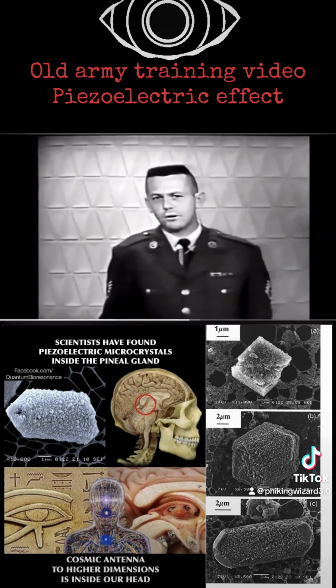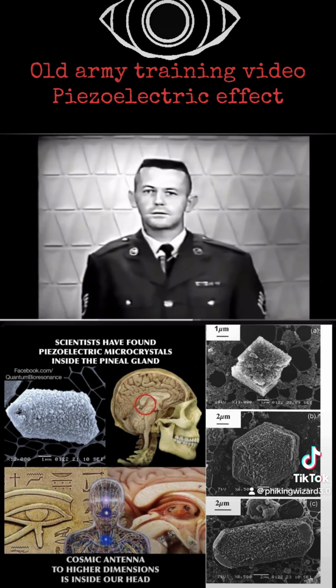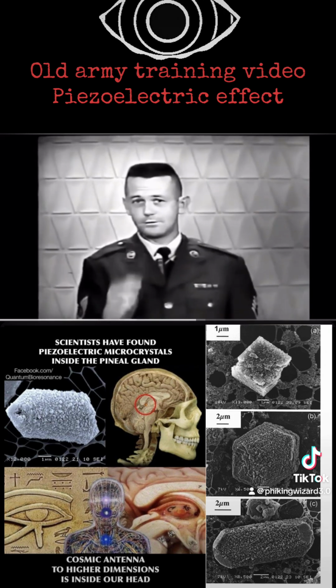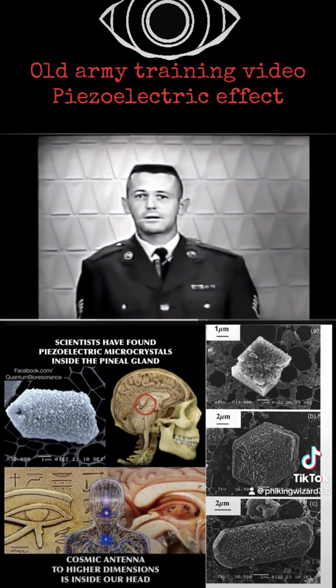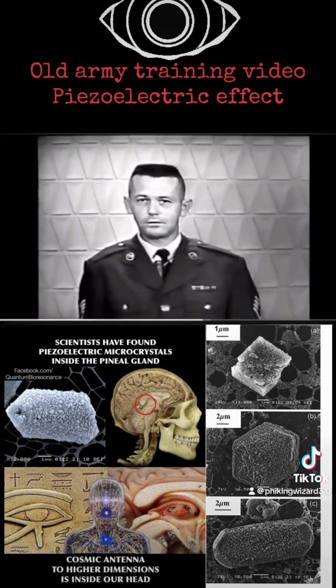Now, in order for a crystal to be used in an oscillator circuit, it first must be placed in a holder. The crystal holder will support the crystal physically and provide the electrodes by which this voltage is applied to the crystal. The holder must allow the crystal maximum freedom of vibration at all times. Let's look at this drawing of a typical holder.